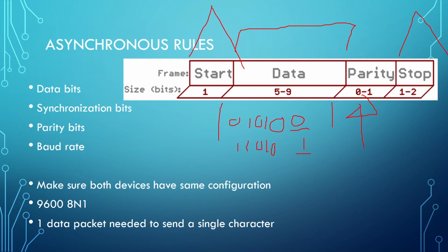This is why I say we only can detect odd errors. All right. So if only one thing gets flipped, and instead of getting 1, 1, 0, 1, 0, you get 1, 1, 1, 1, 0, with our even parity there, you would say, that's 5, I'm doing even parity, something's wrong. But if 2 things got flipped, it can't detect that because one went from 0 to 1, one went from 1 to 0, and I still have even parity. So it can only detect odd. Even if you have odd parity set, it still only can detect odd numbers of errors.